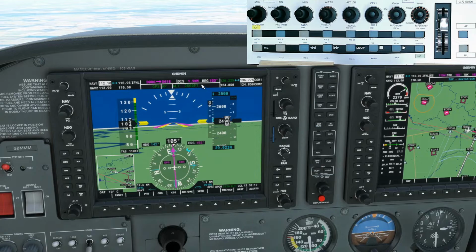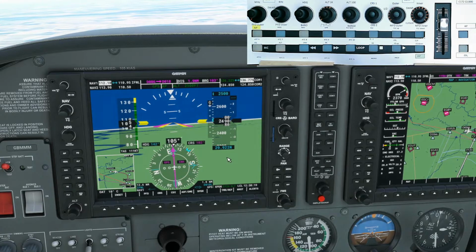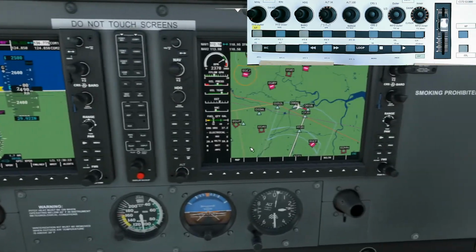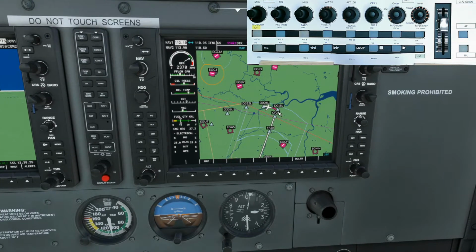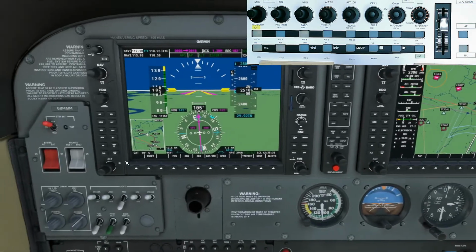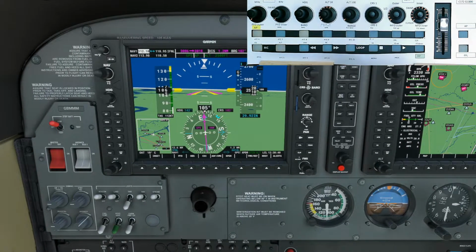So we've got about 2 miles to go to this turn point here, and that then should bring us in here. And what I'm going to do is take a bit of airspeed off now, because I don't really want to overshoot. So we'll pull back now, start to lose speed, and I'm going to go onto a richer mixture.